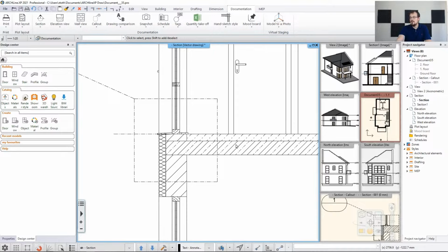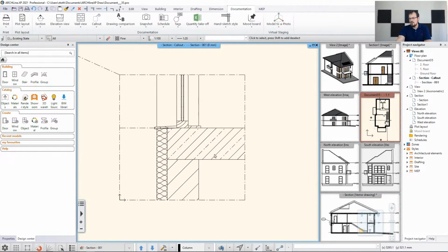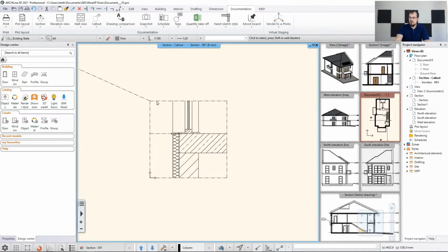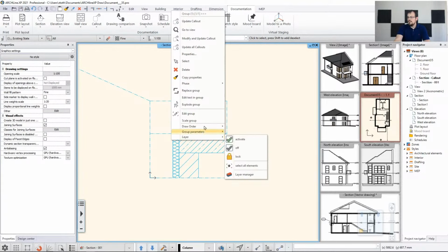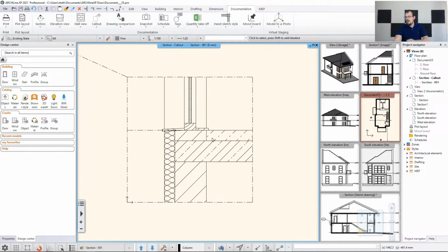Last thing we have to do, we have to make sure that these changes are reflected on the callout, because on the callout we still only have one layer, so this is not the end result. The end result would be a nice 2-layer structure with the floor, with the slabs and the walls meeting with each other the right way. So it's simple to do it. You just go to the local menu of the callout and you just have to say that you want to update. Well, you can update this one, or you can update all the callouts. I'm going to update now this one because that's the only one I have. And now I have an updated drawing of the original version. So I now see a very nice interaction of layers, which I'm going to use for further editing.